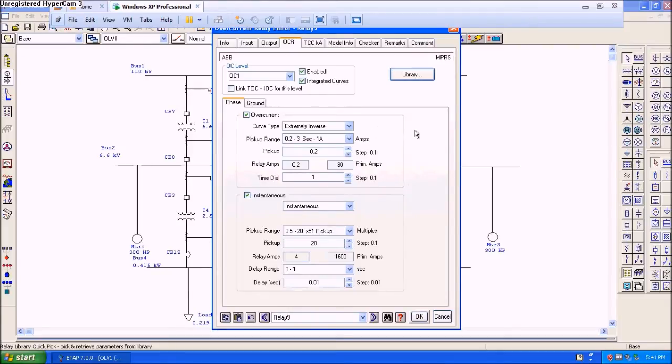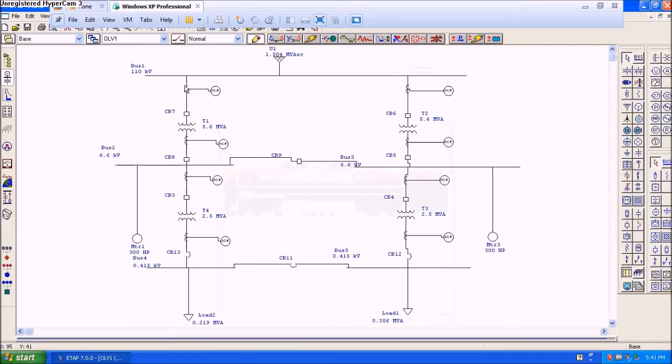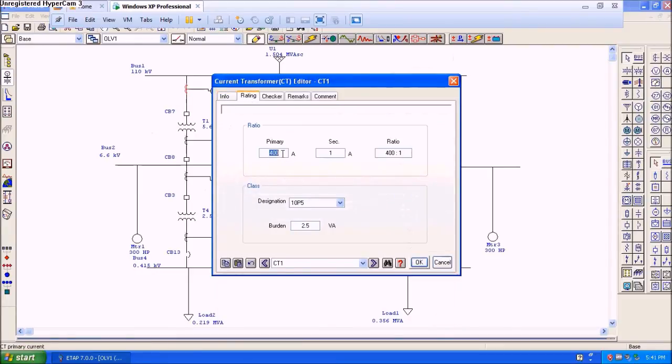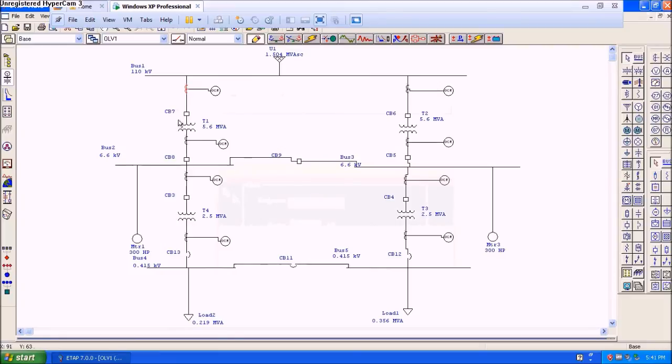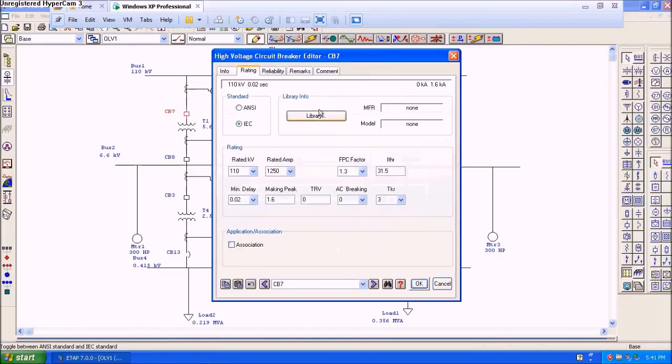Now we will show you the short circuit analysis. So you can see the currents which are flowing in the circuits are red in color. Now we will create a fault. Though we can create a fault anywhere in the circuit, for the purpose of showing, we will create it here, near relay 6. Now if a fault current is here, then relay 6 will definitely operate first, then relay 5 will operate, and then relay 7 will operate, which we can see through a curve.